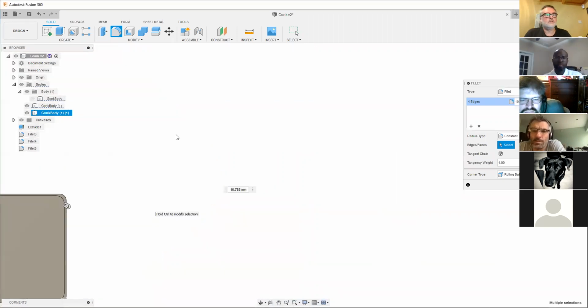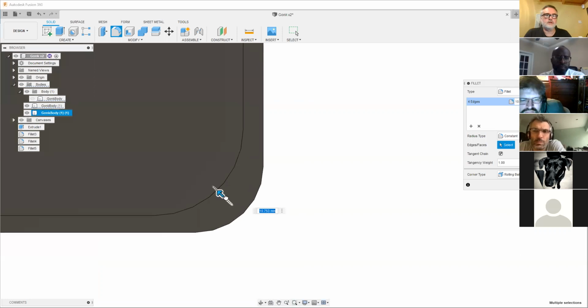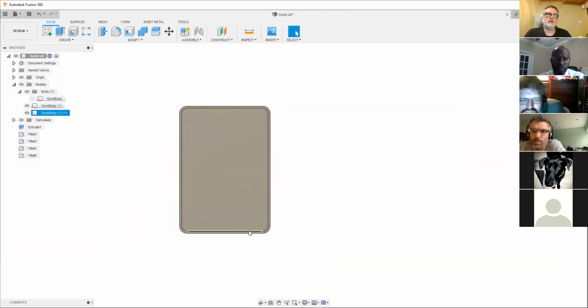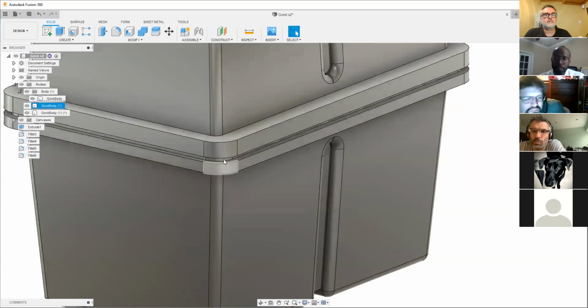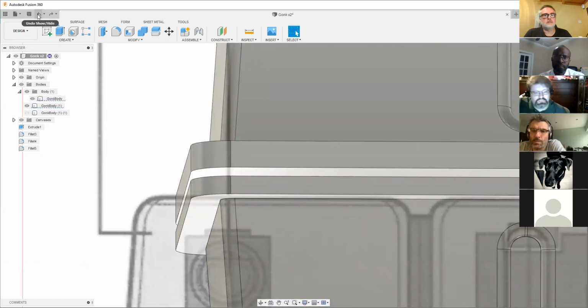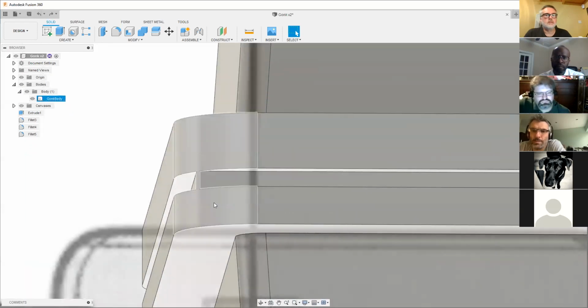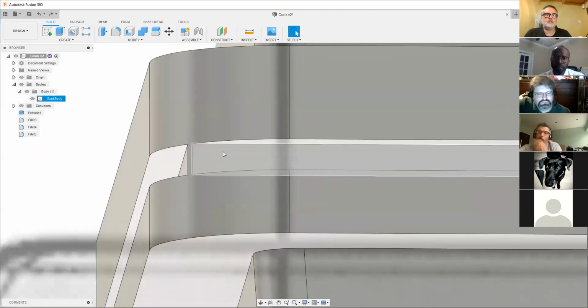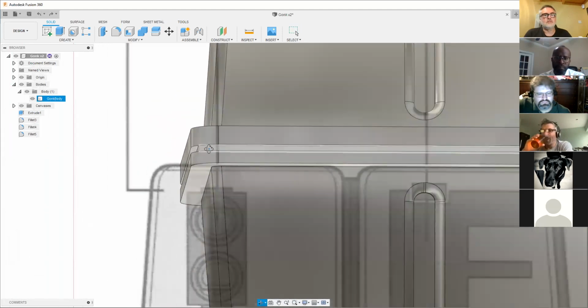The reason I've done that is when we did it before, it was following that same curve, but as I brought it further in, it just snapped out and went, no, you can't take it to that angle, because I was using this as a reference. So by deleting those and pulling it back, I can choose the angle that I want. So I'll click it out there, click OK. And now I'm happy with that, and I can bring that one back in. The reason that I cut it is, if I didn't cut it and I just pulled these back, I'm actually pulling the details of the edge back as well. So I needed to use this section as a separate body.